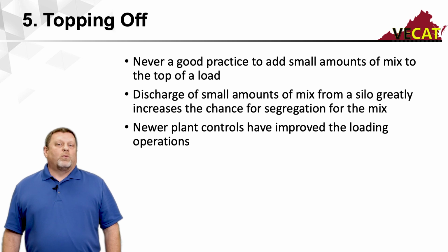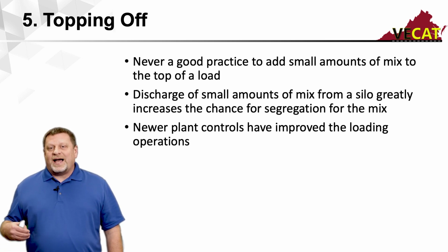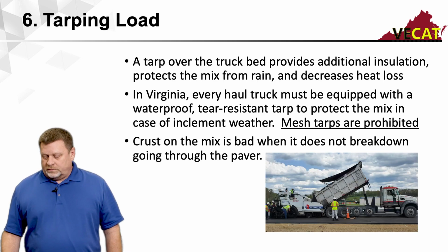But the reason you don't want to do a lot of topping off is if that last drop is a very small quantity, it will tend to segregate on the top of that load, and that's a major no-no.